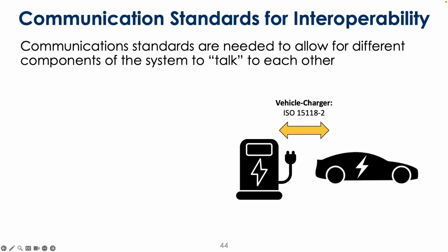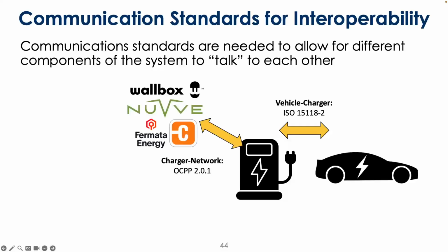So what sort of standards are there? Talking about the communication between the vehicle and the charger, this is ISO 15118-2. This is the communications protocol that is being updated to allow for interoperability for V2G. It already exists as a standard, but doesn't cover, I would say, robustly V2G protocols.